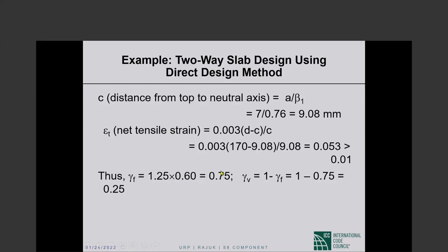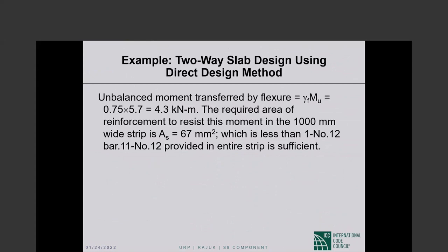So that is the limited flexibility that is allowed at an interior joint, very much less than what we have at the exterior support. But this again can be meaningful when we are doing wind or seismic design, because we have huge unbalanced moments at the interior support sections.